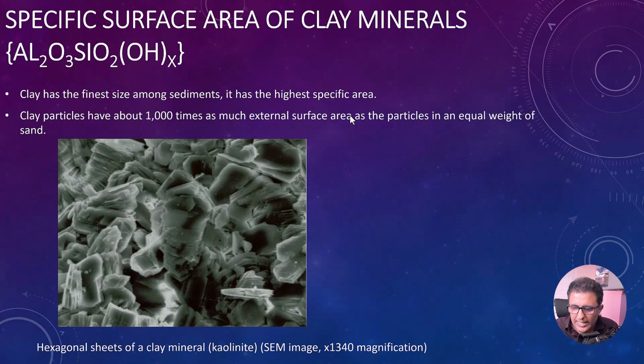Look at the grains that we mentioned before, the sediments. We know that clays are the finest sediments that we find in nature, and for that reason, we can say that clays should have very high surface area. In addition, there is a strong attraction between the clay minerals and water molecules.